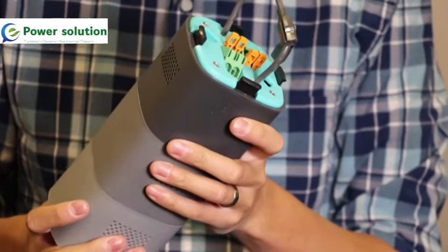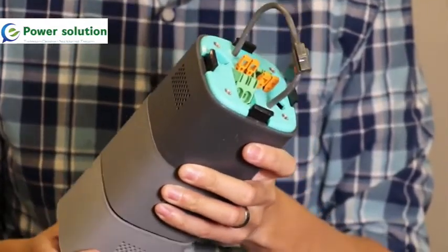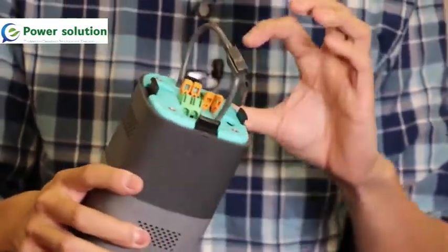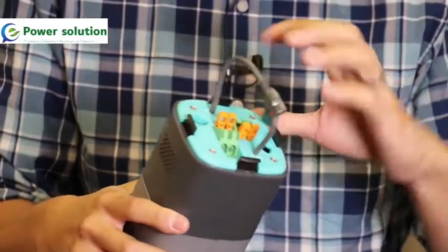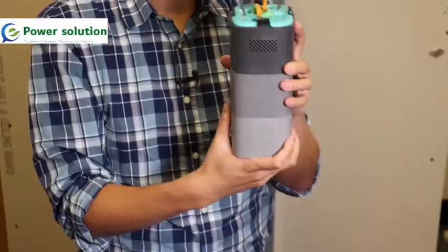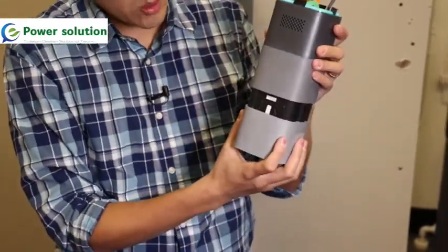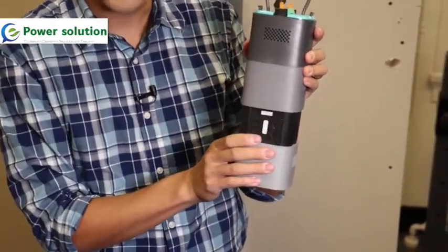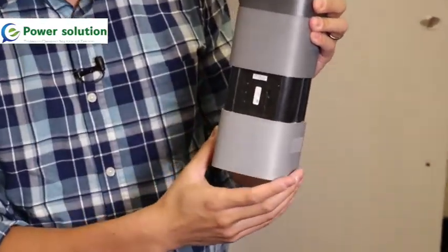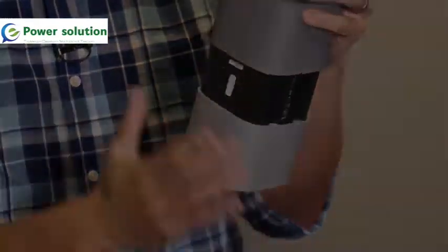The system is designed for 480 volt Y connections. Be sure that you do not put 480 volts across neutral and any other phase because that is beyond the specifications of the system. We like to mount it on the side of the panel, left or right side, and be sure when you mount it, there's a slide-out compartment on the bottom which has diagnostic lights, that the diagnostic lights are visible. Obviously, if it's pointed to the panel, you won't be able to see the diagnostic lights.